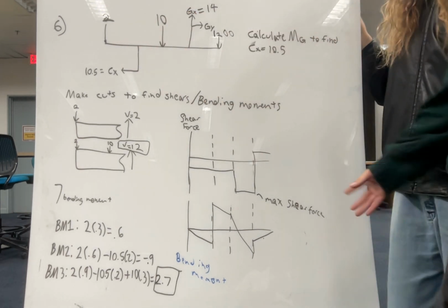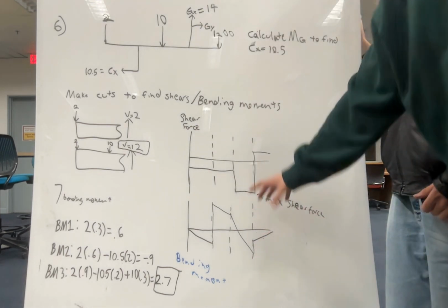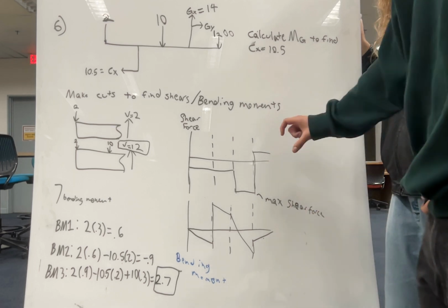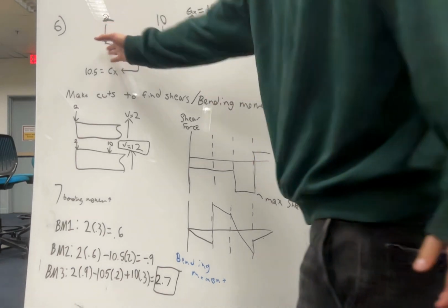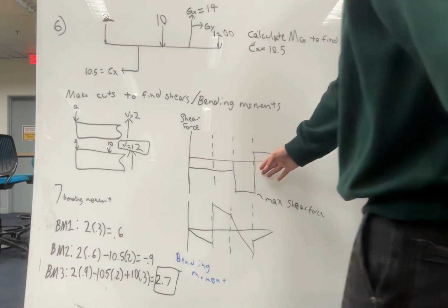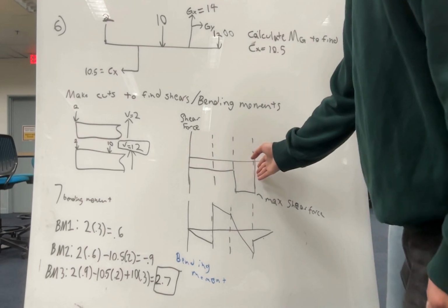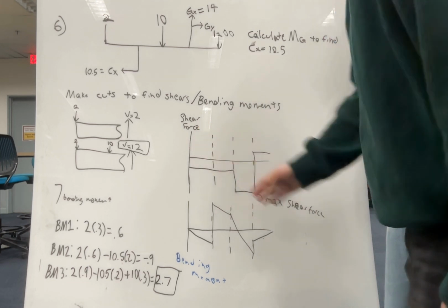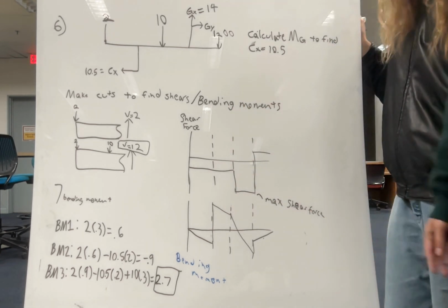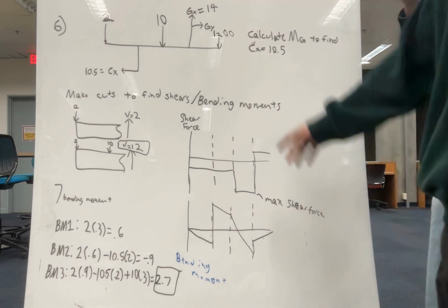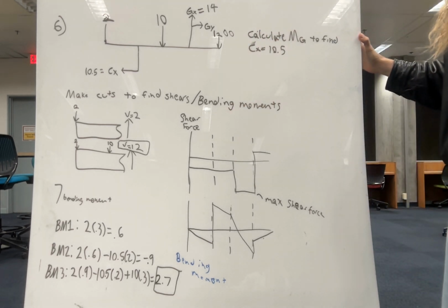You can see using a graph where the most area is, because if this was 1200, it would be all the way down here. The whole reason we took the bending moment from here to here is because the area under this curve is the bending moment. So the most amount of area from one side to another is here. It's just greater to go from here to here versus from here to here. If this was 1200, you'd see it skyrocket, so you'd want to go from that side. I suppose that makes sense.